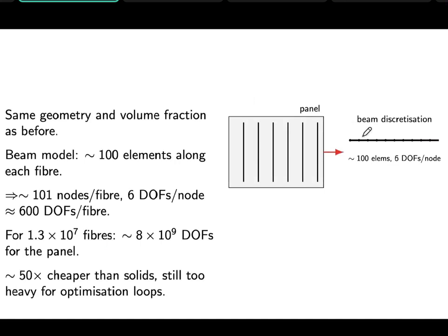Now, the other way, and this is a very good modeling question, is how do I model the beam? Well, I can model it, as I said before, using a cylinder, but I can also use an actual beam. And the actual beam now can bend. That means that not only can each point displace in the three directions, as we talked about before, but we can also have a rotation around the first axis, the second axis, and the third axis.